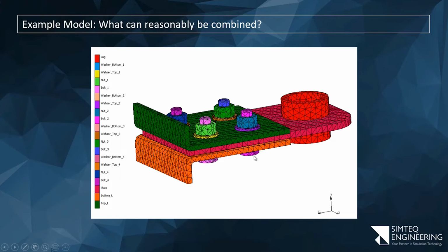I can at the same time combine all of the washers at the bottom and call it the same washer because, well, this one will touch the green part, but the bottom one will simply touch the orange part. Again, the same settings. It's the same materials, same quality of work, whether it's of the surface finish. So the friction coefficients should be the same. If I want the top one glued, I'll probably want the bottom one glued. If I want the top one touching rather, I want the bottom one touching as well. So I can simplify this.